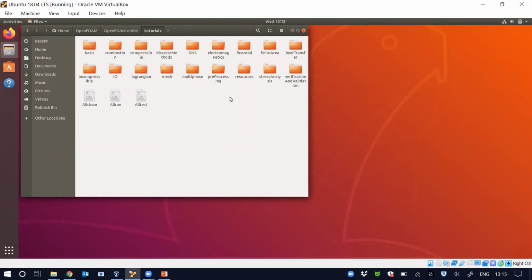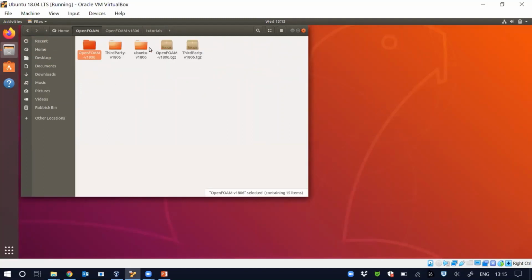And here's a notification for you. When you're modifying a tutorial, it's better to first copy the example code to our own directory, which was created when you installed the OpenFOAM software. For me, it's stored under the name you created and in the run folder.